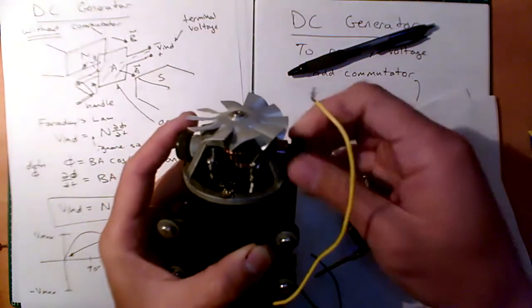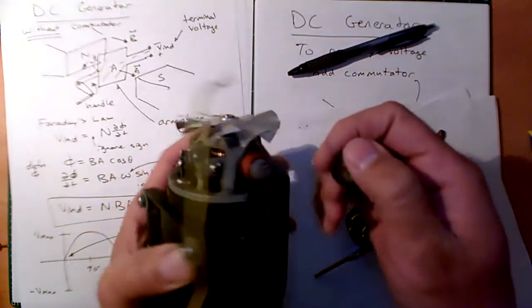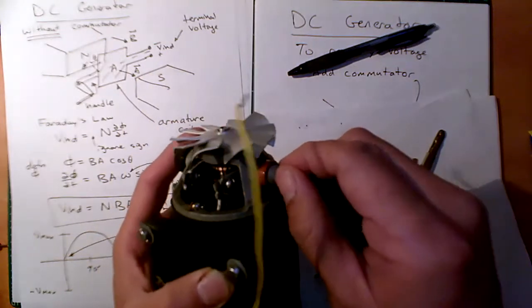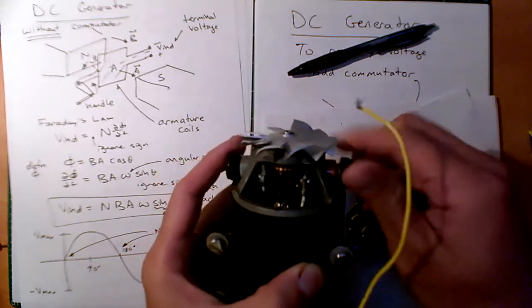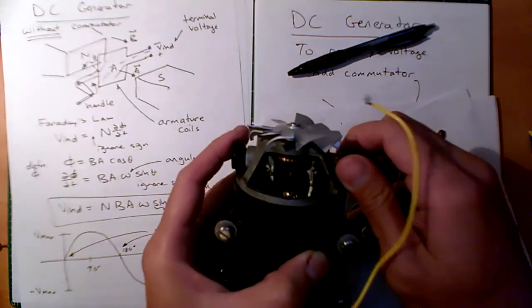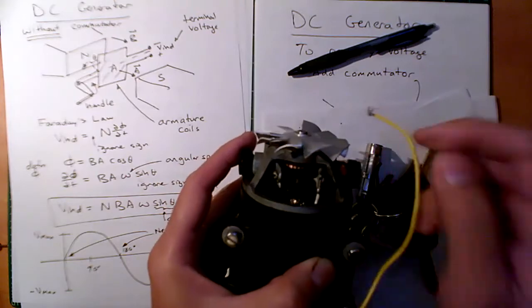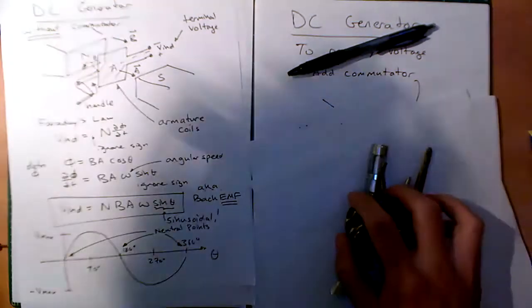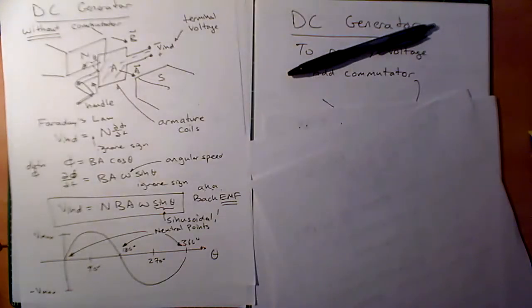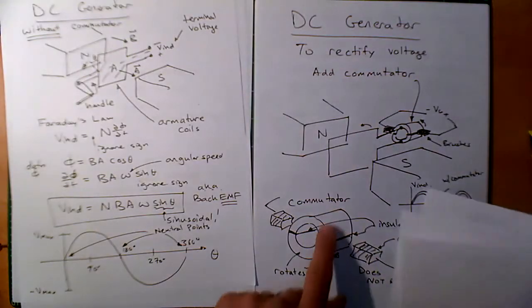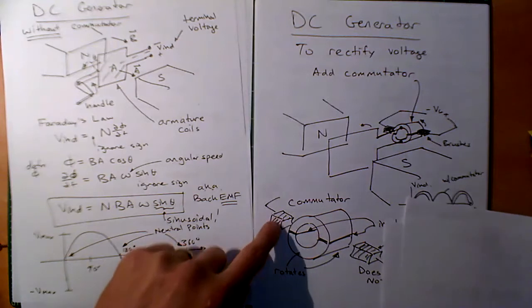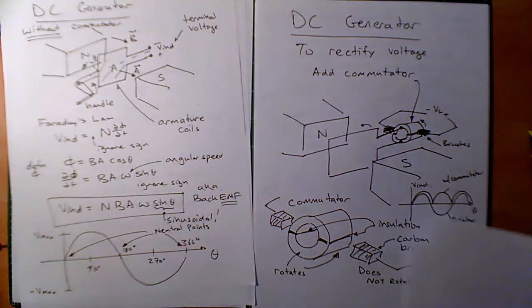I wonder if I can actually take out the brush. Let's see, does that pop out nicely? Maybe it doesn't pop out nicely. But you can imagine this would be a maintenance item, right? So brushes wear out, and this is something that would need to be replaced, and maybe you might have to shape it so that it conforms to that face. See how you might have to grind a nice round face in there.